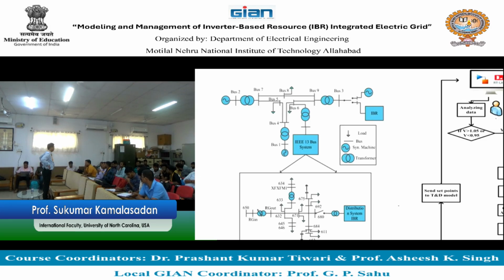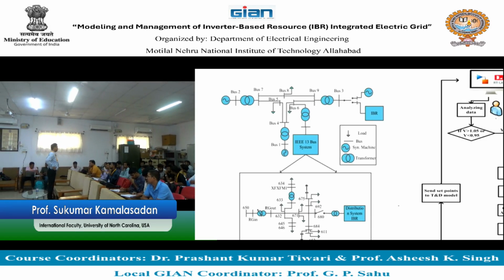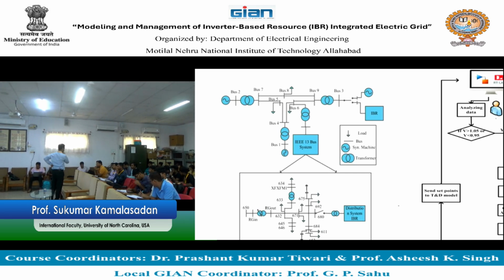So there are two models that you study very extensively on transmission networks. One is the IEEE three-machine 9 bus, and the Kundur two-area system model, so it's a two-area model. This three-machine 9 bus is actually a real system, an aggregated representation of a real system in some part of the United States, which has a lot of oscillations between those. So it's basically used for oscillation study. So you have three machines there, and 9 buses.